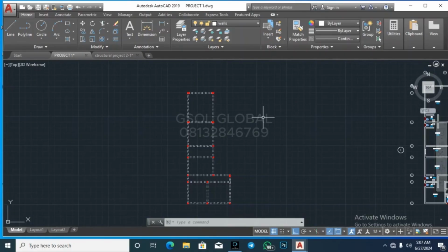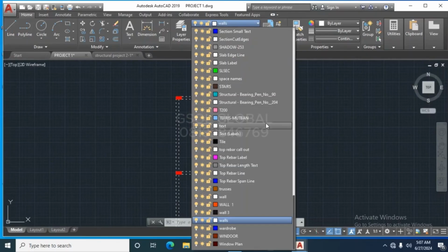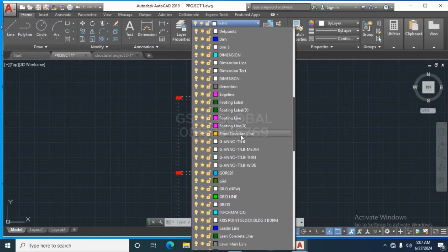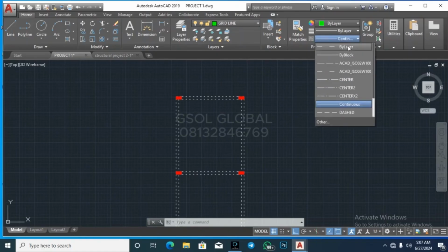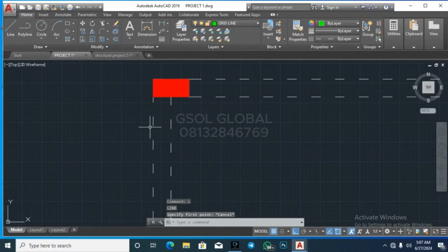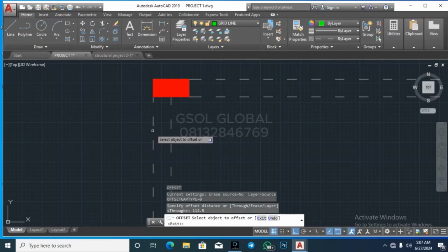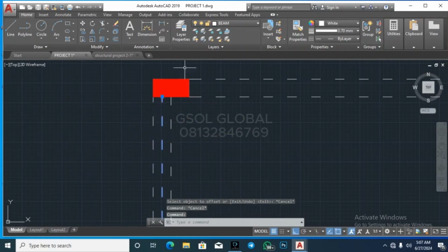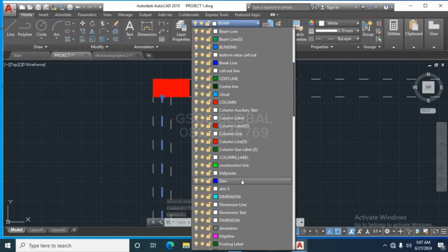All right, so for the grid lines, I'll locate the grid line we created here before. Remember I told you guys you can draw on the same interface. So we are drawing on the same interface, you can do it. By layer, that's what we are working with. So we can just offset one of these 112.5 to the middle. Then we can convert this to our grid line by putting it inside your grid line layer.